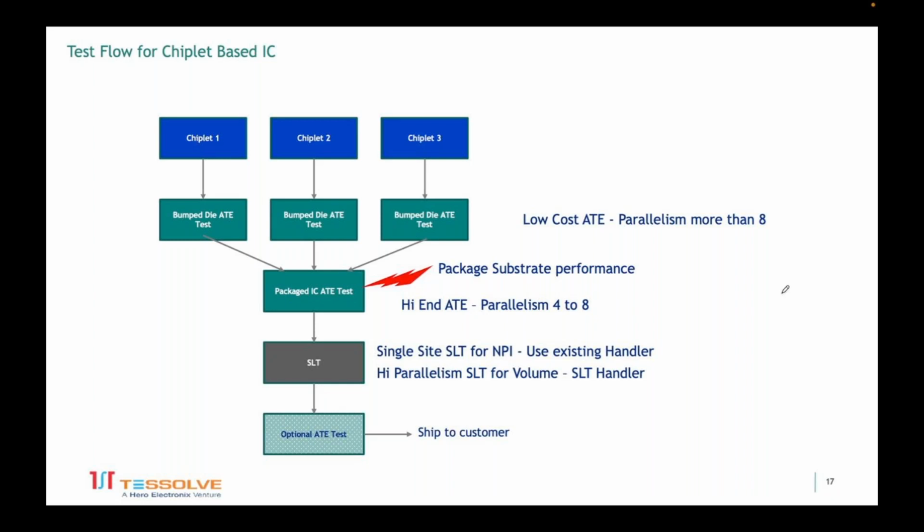So you need to look at this point of time: for a chiplet-based solution, test cost is definitely a key aspect versus a monolithic integration. But certainly for a given process node, if your reticle size is almost 70 to 80%, then chiplet-based is the right approach from a scalability and future perspective.